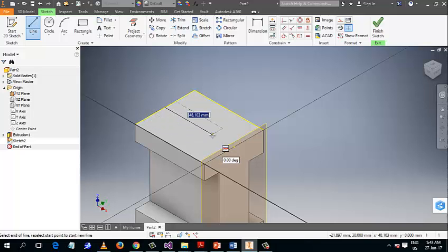Then press escape. Come here, click another line. It will just be like a dimension line. Click here, come here. It's aligned vertically at 90 degree. So let them cross each other, and the intersection will give you the midpoint. I think that is simpler and better.